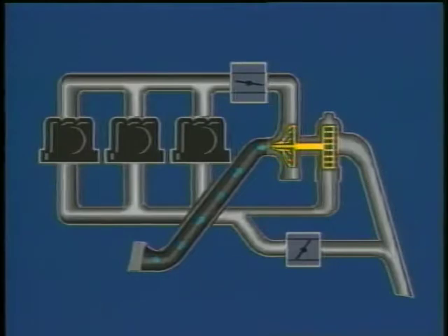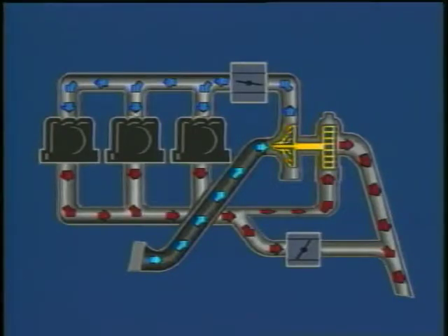As air enters the intake, it passes through a compressor where it is compressed by the centrifugal force created by the impeller blades. The compressed air is then routed from the ring surrounding the impeller through the throttle body to the cylinder. The compressor is driven by a turbine which is propelled by the engine's exhaust. If all of the exhaust from the engine were allowed to pass through the turbine at low altitudes, the compressor would produce excessive manifold pressure and high operating temperatures.